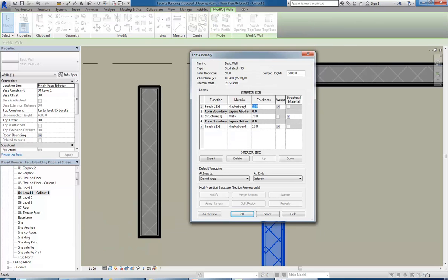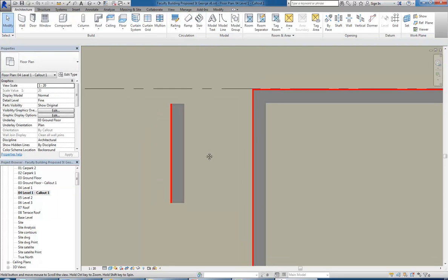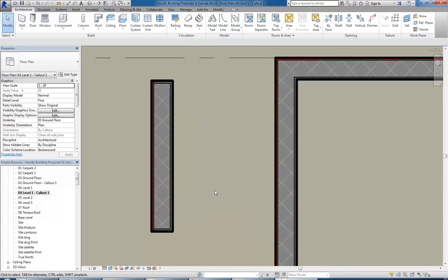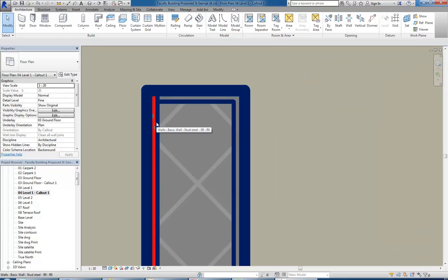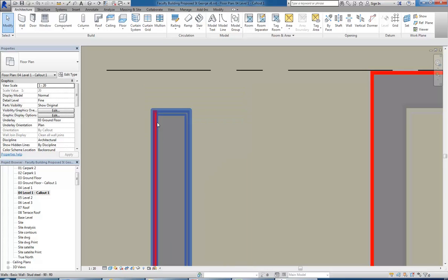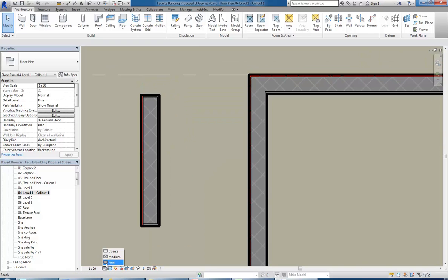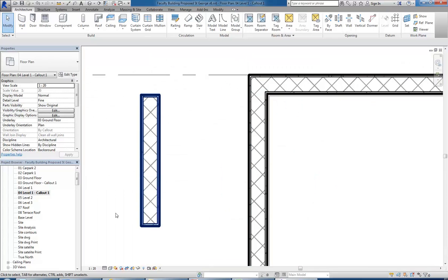But then just to finish up with the basic options you have with materials, if I click OK here, you can see there that we now have the shading colour set in the plan view, which is often not what you want. So I'm going to go back to hidden line, and you can see that it won't use that colour anymore.